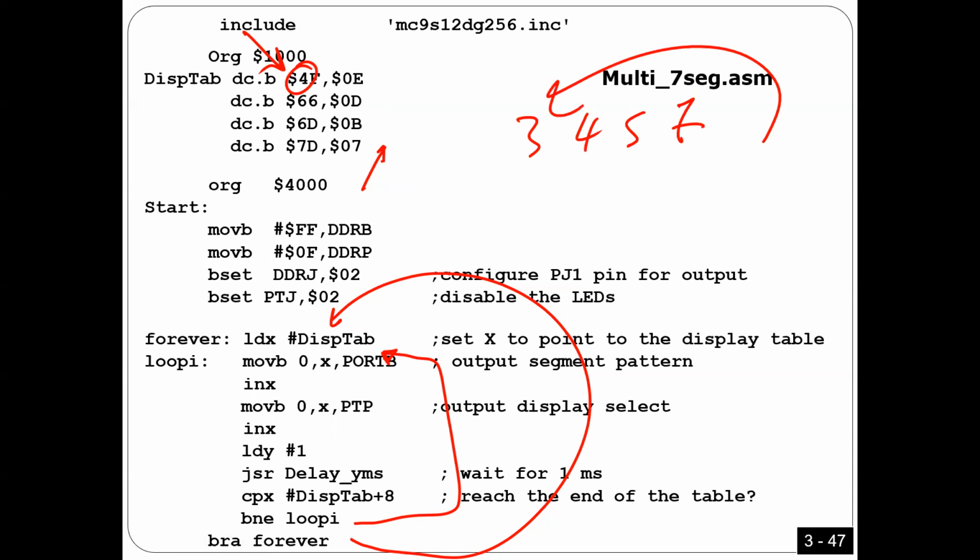And that's what I mentioned before comparing to LCD. In LCD, if you want to display a number, you just write this number one time, right? Because internally, it has a system that can do the work. However, here you have to keep doing it. So you have to write 3, 4, 5, 7, 3, 4, 5, 7, and so on. This is different from LCD. That's what I want to say. Any question, guys?